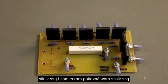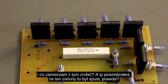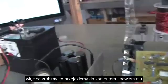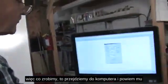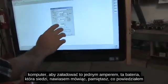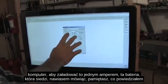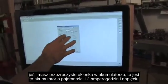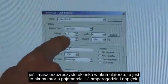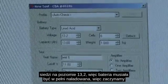So there it is, right in front of you. And what I'm going to do with this... And you said that green one was the trigger one? Right, right. So what we're going to do is go over here to the computer, and I'm going to tell the computer to load this at 1 amp, this battery, which is sitting, by the way, remember what I said about if you had clear windows in the battery. It's a 13 amp hour battery, and the voltage is sitting at 13.2. So it must have been a fully charged battery.